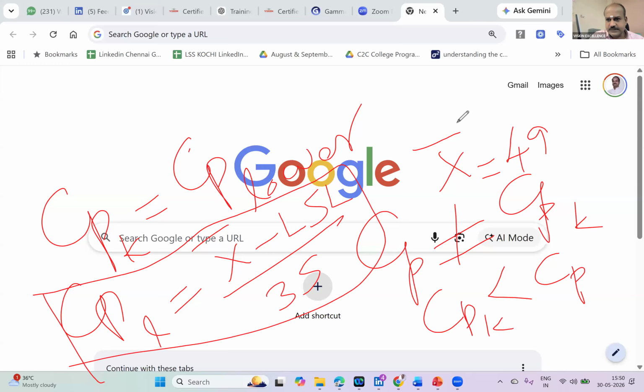I think now all of you have mastered this subject, CP/CPK. Will you be able to really apply this for any situation? CP/CPK analysis is required if you are measuring the capability for measurable characteristics. Let us say coating thickness. Can I calculate CP/CPK? Yes. Diameter. Can I calculate CP/CPK? Yes, sir.